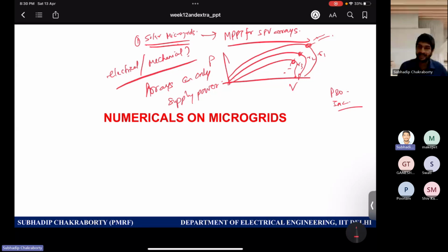If there is a battery, there will always be specifications of the battery. Otherwise, when we say solar microgrid, it implies an AC microgrid. If they are tied to the grid, that statement will be given to you. They are tied with the solar photovoltaic array, interfaced at the DC side, and in the middle there is a converter, the solar inverter. So that is the configuration.